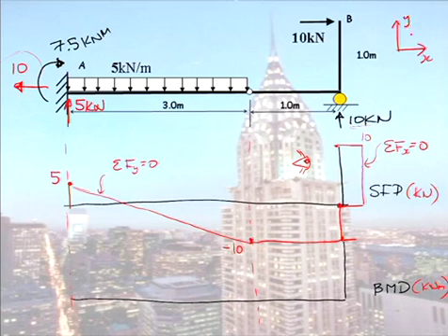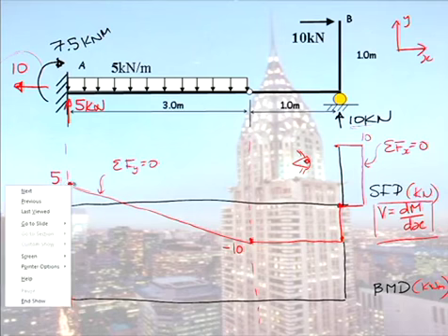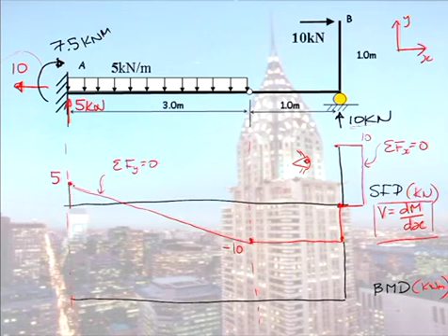So the shear force diagram is a plot of perpendicular force. Oops, I took the whole thing away. Now the important thing to remember: your shear force diagram is your shear force diagram, but it's also the slope, or the gradient. The value here of 5 is telling me the slope of my bending moment diagram has a value of 5 at that point.